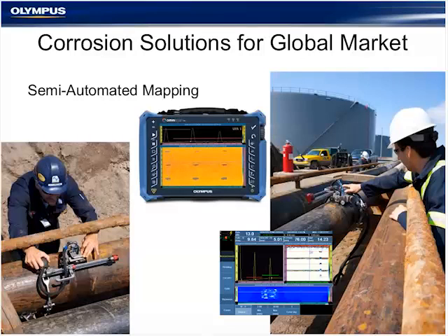And it allows you to essentially draw what you see on the screen there, which is called a C-scan. And this draws a map of your part, a swath of area that you wanted to cover. And so if you have an isolated area where you're concerned that the corrosion might be very much different from one point to the next 3 inches over, this allows you to be very, very thorough with the mapping of that particular area and get a full 100% coverage of that.